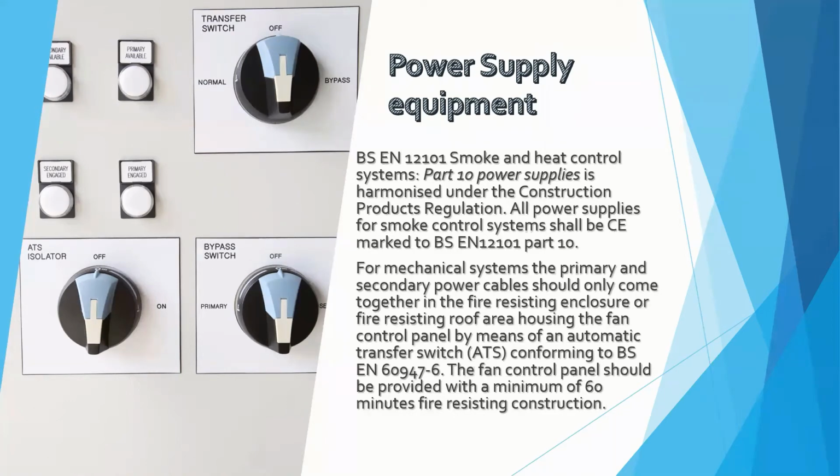Control panels should be located outside the fire zone, together with the power cable and the fan control panel, with the enclosure fire resistant for 60 minutes. That ensures that the smoke system continues to work or be isolated in times of fire, in support of the fire teams.